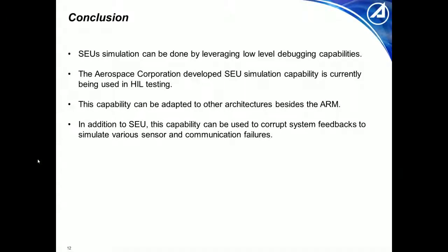Yeah, this is Mike Aguilar. I think you might add to your slide here, not only is this single event upsets with the tool suite you have, but many times you want to test out your watchdog timers. And you could use this tool to corrupt some instruction stream so that you can actually fire your watchdog timer without having to put some artificial watchdog timer command inside your software. It just might be something you add as a use for this tool, as a test for watchdog timer corruption.